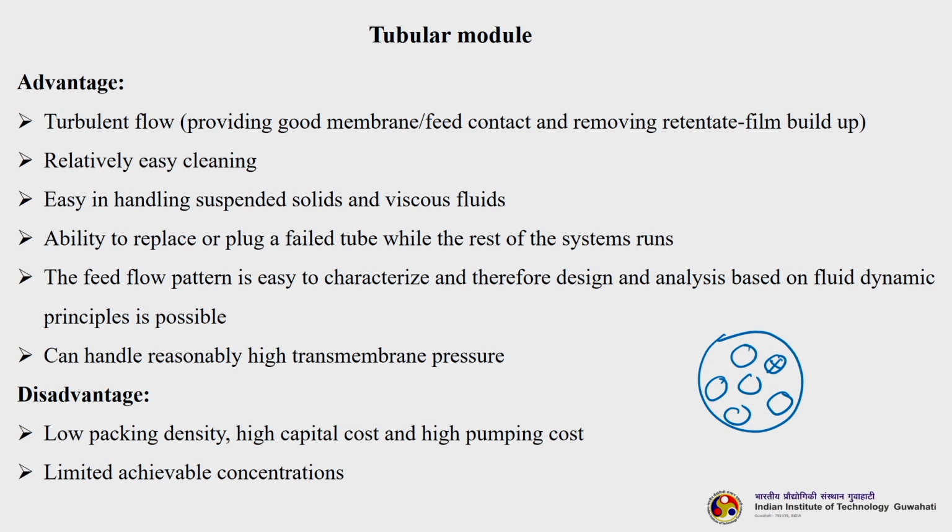I can either open the membrane module and replace this particular tube with a new one, or I can plug it. I can seal it from both ends so that tube is not taking part in separation. That is why this type of tubular system is really advantageous when we are using it in industry or large scale applications.